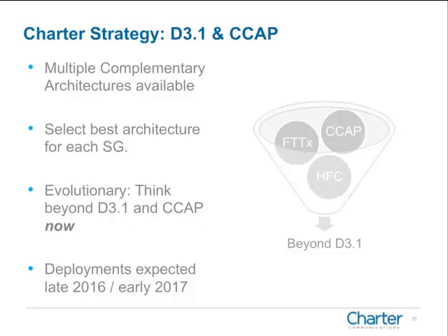So we've got your traditional CMTS, CCAP type architecture with large head ends or large hub sites, and the architecture that we all are familiar with, traditional HFC. Going down in the future, you've got remote PHY, you've got different flavors of that with remote MAC-PHY, you've got remote CCAP out as a potential option. There's RF over glass, which plays into when IP video and that transition actually takes place, as well as ultimately going fiber deeper, which can mean either reducing node cascades or even fiber to the home or fiber to the business.